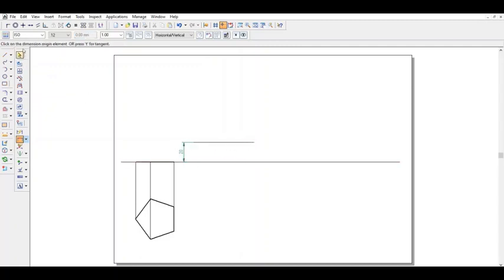You must also show the dimensions of these two. Also find the dimension of these two things here. Now in this case, since he has not given an angle, you will select the whole thing and go for move. Make sure copy is active. So make a copy of this. When you are rotating this, since he has not given any angle, just select the end point of this one.